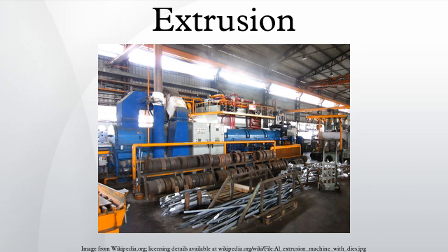The glass melts and forms a thin film, 20 to 30 mils, in order to separate it from chamber walls and allow it to act as a lubricant. A thick solid glass ring that is 0.25 to 0.75 in thick is placed in the chamber on the die to lubricate the extrusion as it is forced through the die.